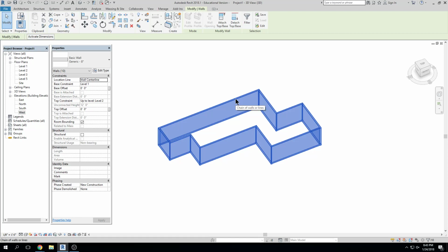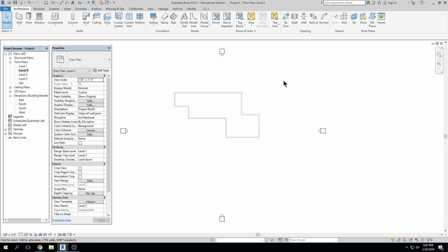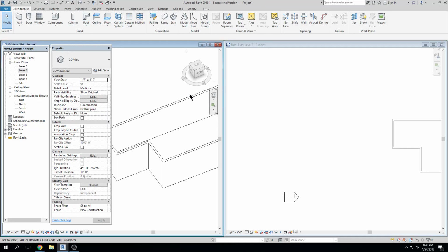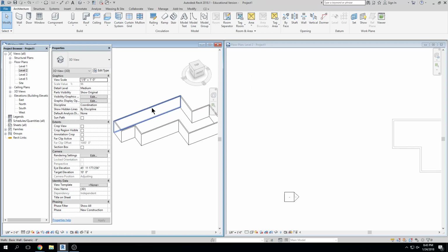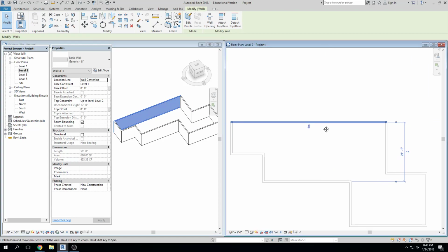So if you select any partition, how do you, like, split the wall in half, right? Like, you set a partition and make one wall higher. How do you split them? Yeah. So let's go to level 2. We're going to split the wall using the split tool. I'm going to go into 3D here, and we'll do a window tile here. So let's say I want half of this wall to go up high and half of this wall to stay low, right? Which is pretty common.